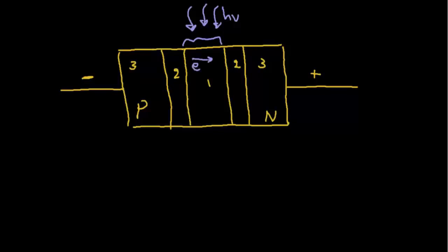The electron will move to the positive terminal, and the holes will move to the negative side. And here the electrons, because of diffusion, this is the diffusion area, are moving this way, and the holes are moving the other side. Here we will have electron hole pairs, and they are wandering, they don't know where to go, because there is no potential difference here, it's flat potential energy.